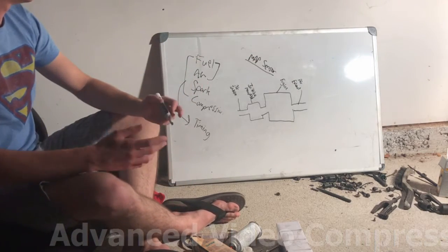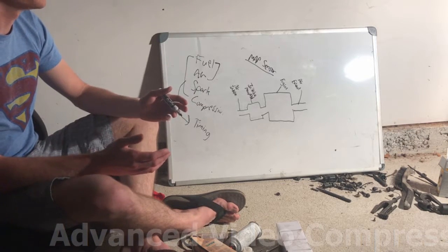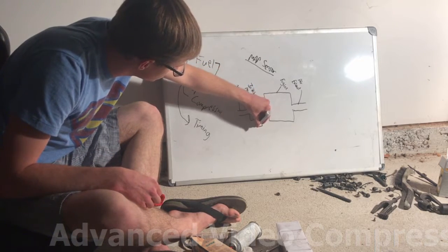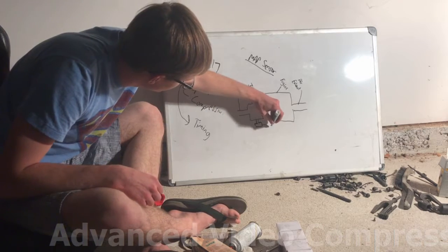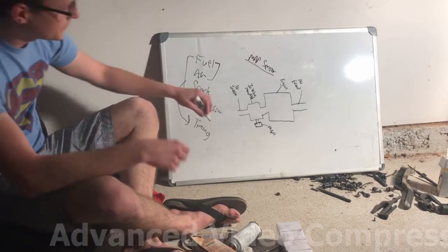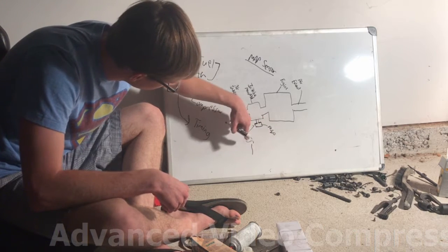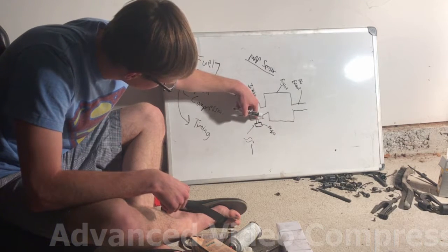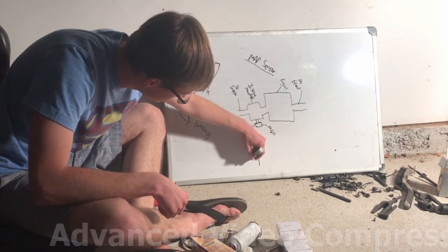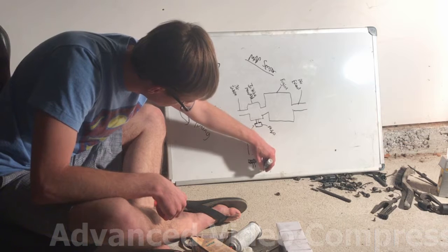So instead of measuring airflow like a MAF sensor does, a MAP sensor actually measures air pressure. And this is generally going to be in the intake manifold. Here's my MAP sensor. Basically, the inside of the MAP sensor is going to look something like this. If this is the bottom of my sensor right here, where it connects to the intake manifold, it's going to have a tube that actually goes up to a diaphragm. And this is a device that looks sort of like a plunger.